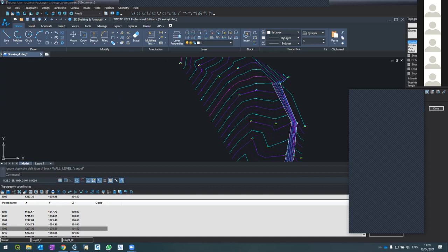To finish, press S in the command line plus enter. Then in the right window, press the new line button, lower row, and repeat the process for the second line.